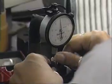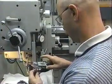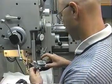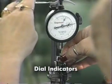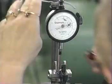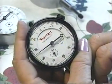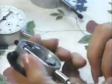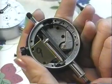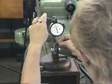Dial indicators and electronic digital readout displays are widely used enhancements for tools to improve the precision of measurement readings. Dial indicators have a contact point which is attached to a spindle or rack. When this spindle or rack is moved, it transmits that movement to a pinion and then through a train of gears. These gears magnify the movement, which is then read off the hand of the dial face of the indicator.